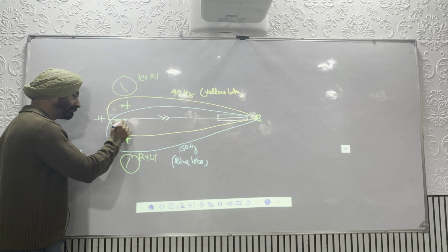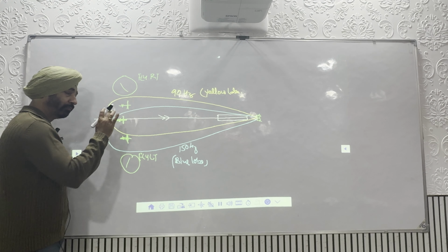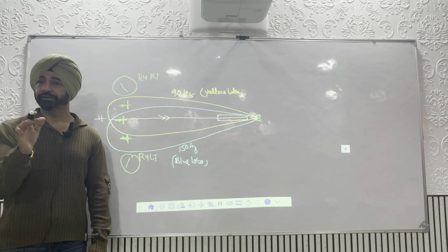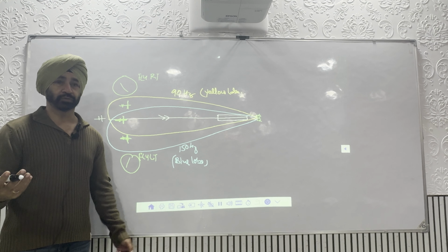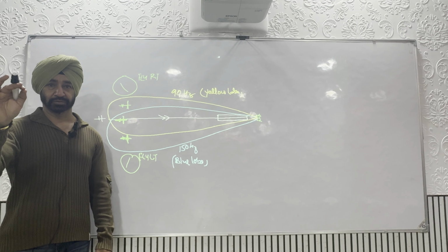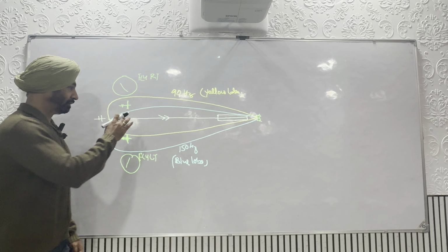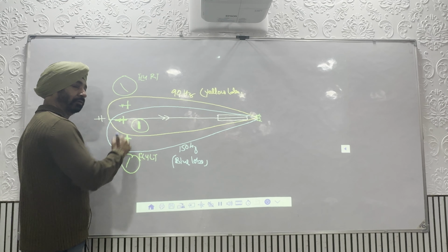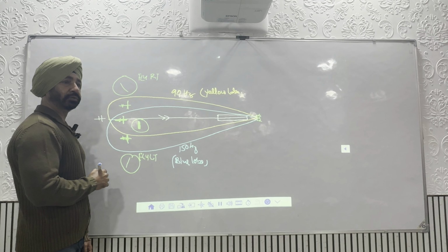And if you are exactly on the center line, both the modulated signals of 90 hertz and 150 hertz will be received in equal strength. The difference in depth of modulation will be 0. So when you are here, your pointer will show continue straight.